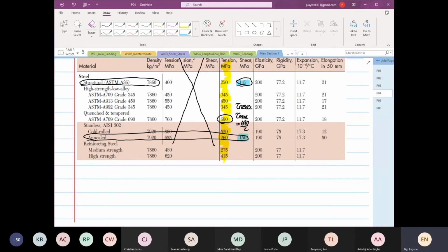Okay, it's safe enough. For optimum structures where you know the stress state, you can use a safety factor of 1.3. If you're unsure of the analysis and you don't know the stress state, you use a safety factor of 10. Right? You are not sure. Civil engineers can use a safety factor of 10.